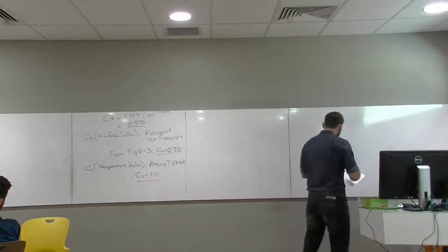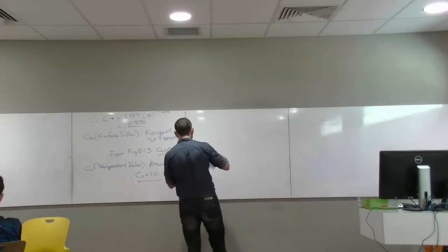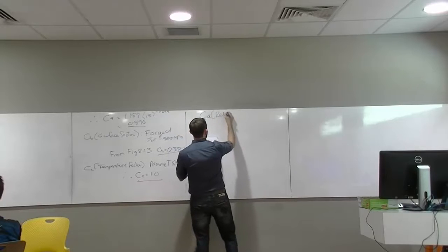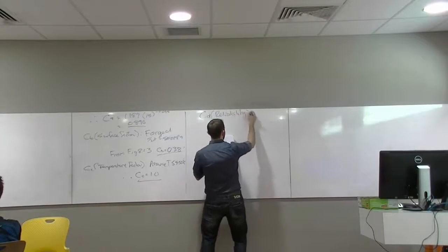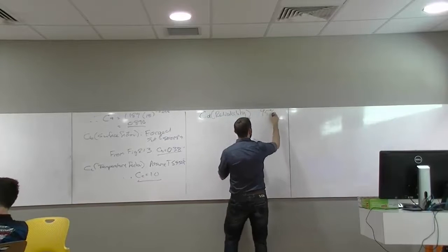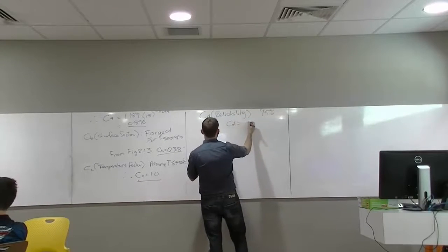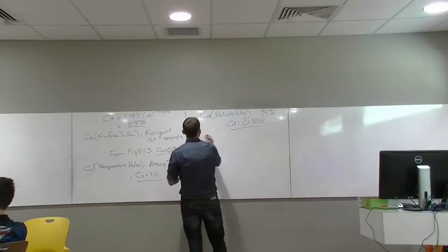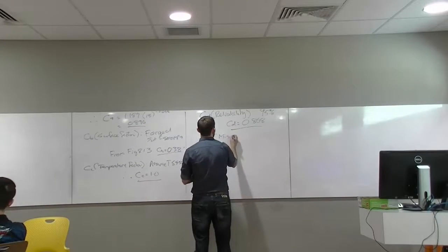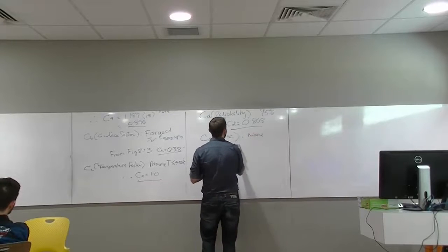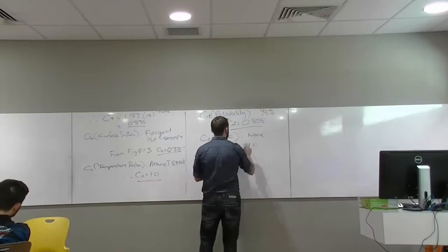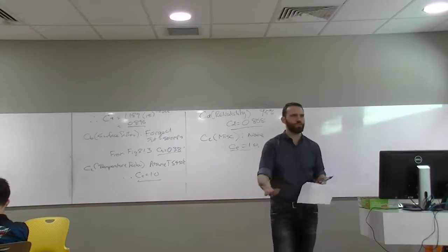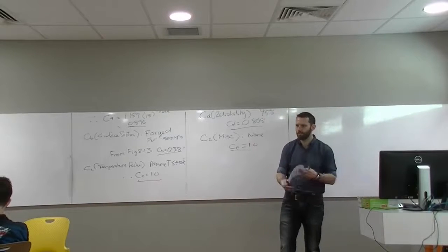CD, reliability, and you're told 95% reliability, which you can read a number straight off the table. What number do we get? 0.868, excellent. And last one, CE, miscellaneous, and I just say none. CE equals 1. As I said, obviously we're not having any miscellaneous effects, but when you're actually doing this, just put it in your workflow so that you think about that every time.